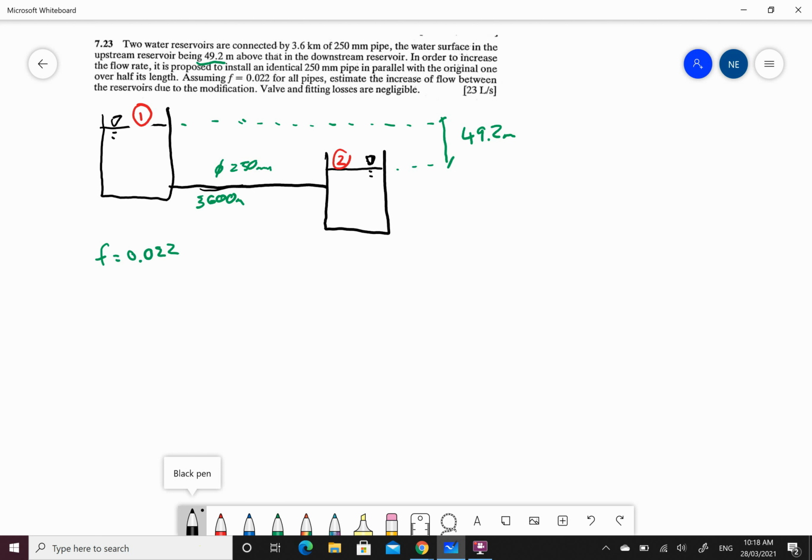So how do I start this? Well, remember the other week we went through this nice formula that lets us calculate between these 2 points. Alright, we have old mate Bernoulli. So H1, P1 on rho g, plus let's do our velocity head, V1 squared on 2g, equals, so this side is equal to H2 and so on. Remember, we're going to have a difference in this one here.